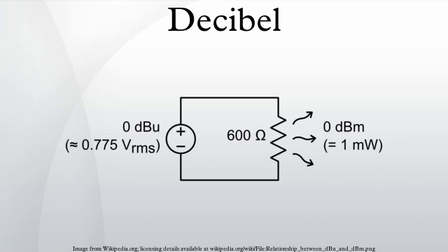In professional audio specifications, a popular unit is the dBu. The suffix u stands for unloaded, and was probably chosen to be similar to lowercase v, as dBv was the older name for the same unit. It was changed to avoid confusion with dBV. The dBu is a root mean square measurement of voltage that uses as its reference approximately 0.775 VRMS. Chosen for historical reasons, the reference value is the voltage level which delivers 1 milliwatt of power in a 600 ohm resistor, which used to be the standard reference impedance in telephone circuits.